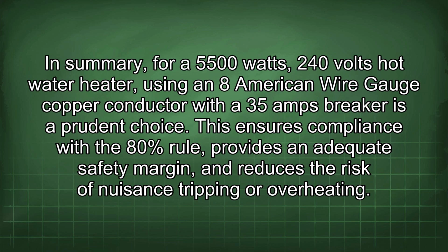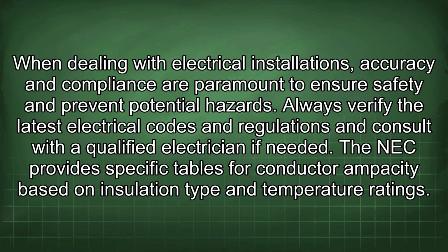In summary, for a 5,500 watts, 240 volts hot water heater using an 8 American wire gauge copper conductor, a 35 amps breaker is a prudent choice. This ensures compliance with the 80% rule, provides an adequate safety margin, and reduces the risk of nuisance tripping or overheating. When dealing with electrical installations, accuracy and compliance are paramount to ensure safety and prevent potential hazards. Always verify the latest electrical codes and regulations and consult with a qualified electrician if needed.